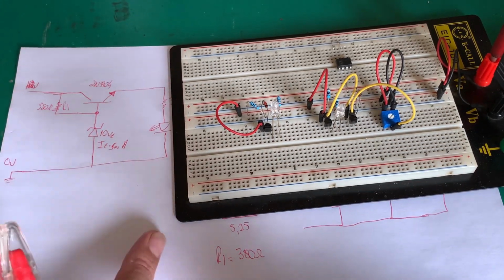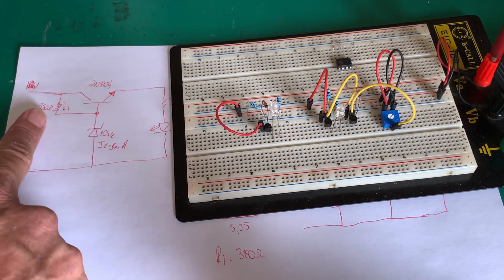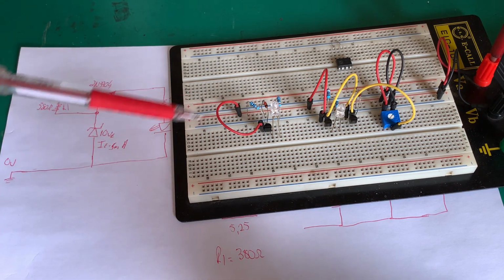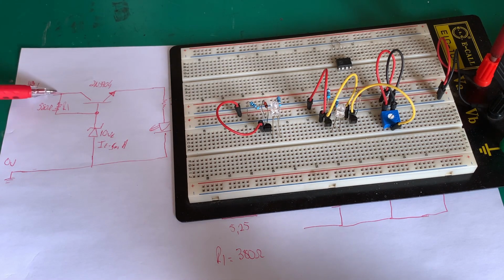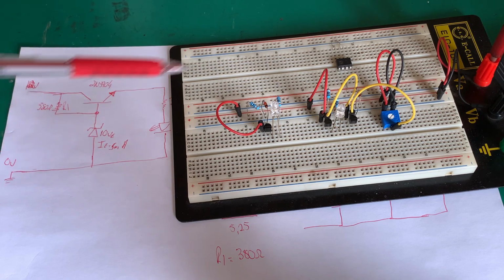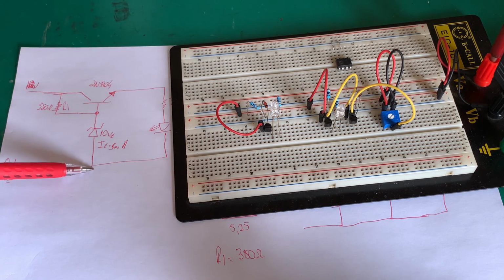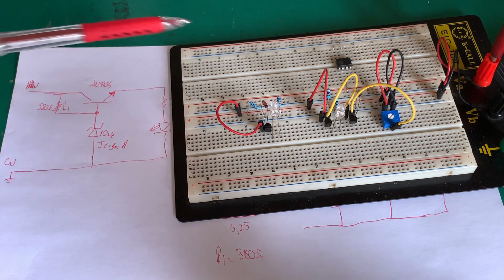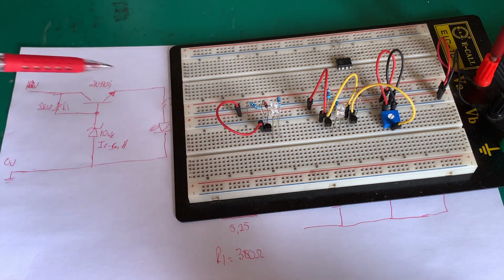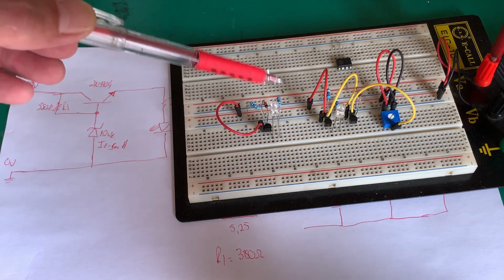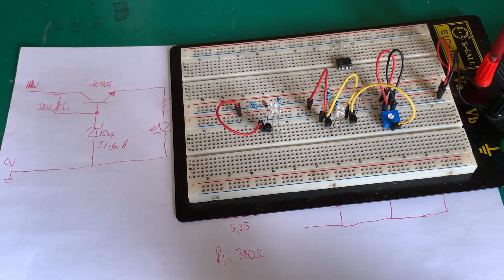You can see on the left, the red wire over here is going from the positive rail to the collector over there. And that's about it. The resistor goes from the positive rail to the base. The base is also connected to the 10 volt Zener, and the Zener is connected to the 0 volt. And then we just have on the emitter side our LED with its current limiting resistor.